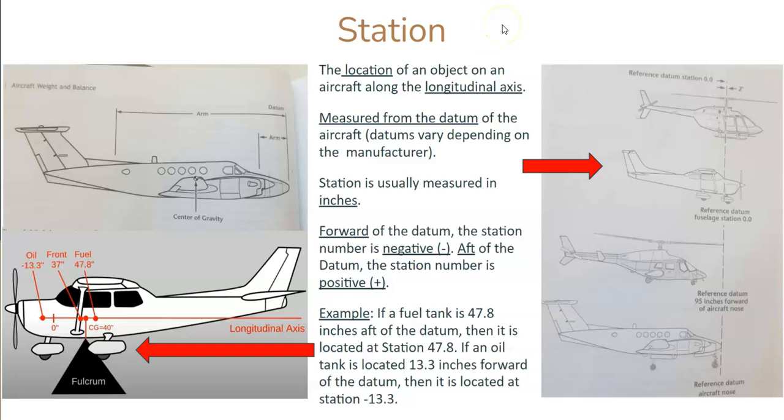One thing that I briefly touched on, but I want to make sure that we understand here. You may remember this image from the last video. You'll notice that when we measure distances and when we're doing weight and balance, it's important to know the distance because, again, distance is part of that moment, that lever arm. The further a weight is away from that balance point or that center of gravity, the more it's going to tilt. A 40-pound gas can will have minimal effect here compared to a 40-pound gas can being over here. It'll cause it to tilt on that fulcrum a little bit more.